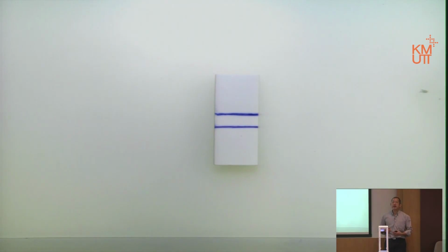What this demonstrates is that if the point load, the axial force, doesn't fall onto the centroid of the area, it creates bending moment. Don't forget, axial force is associated with just shortening, no bending, no curvature, just shorter, longer. The one that causes curvature is bending moment. So, if the point load or the axial force moves out of the centroid for whatever reason, then it creates bending moment. And that is the case we're looking at.